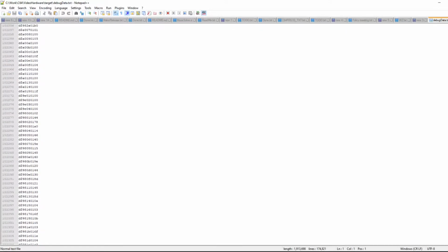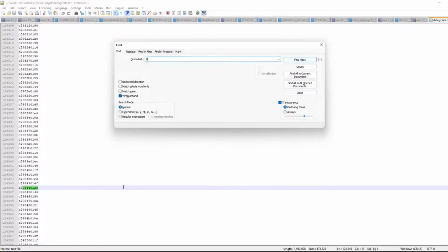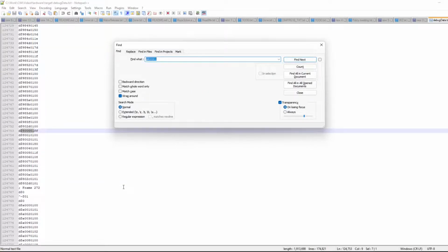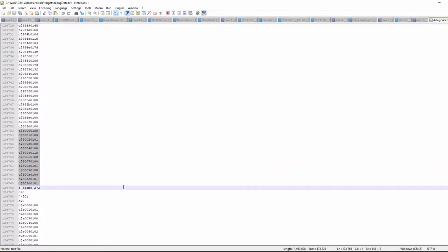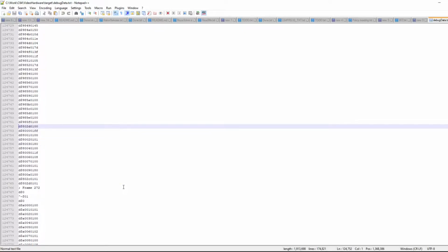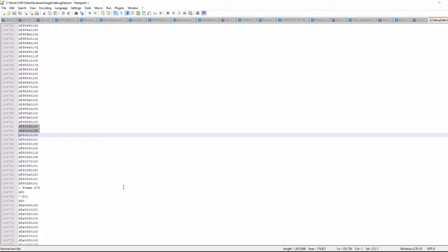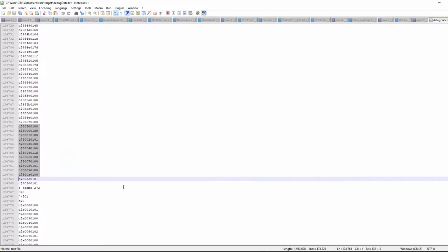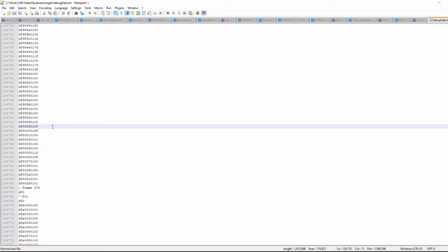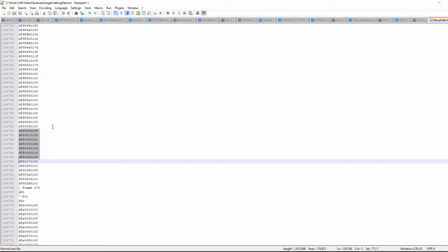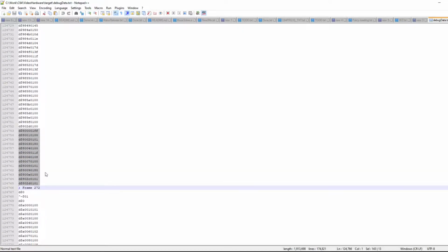On different frames, some of the frames are outputting control to the audio hardware. If I look for that, for example, here, these are writes to the audio hardware control registers. We can see here that the voice is being turned off, and then we're editing some of the voice parameters, and then we're turning the voice back on again for playing the first sample with maximum volume and a different memory address and all sorts of different looping parameters.